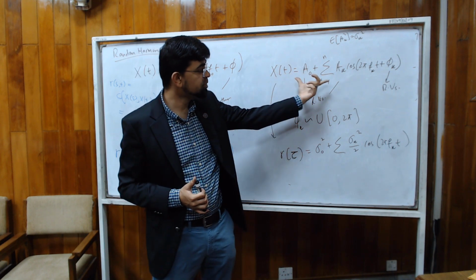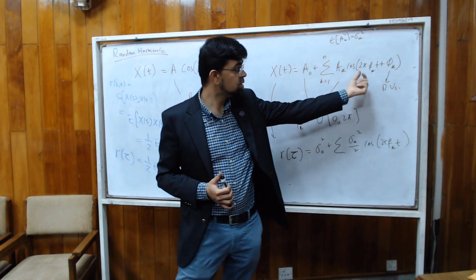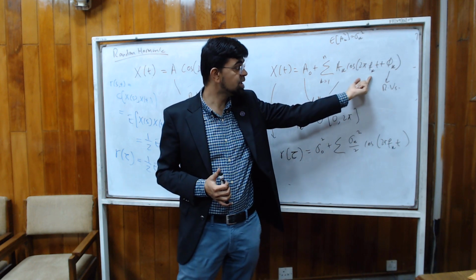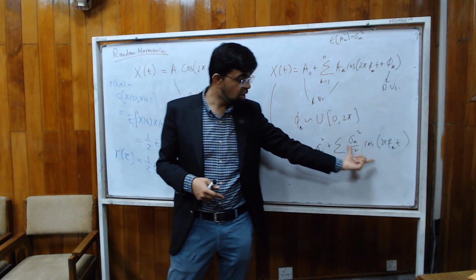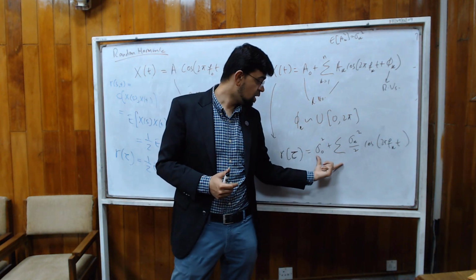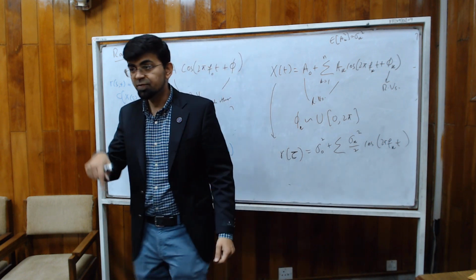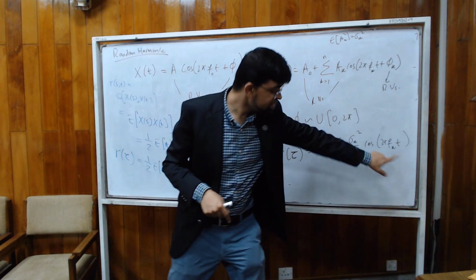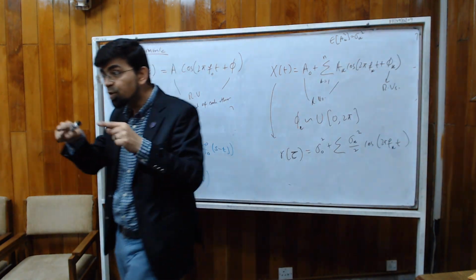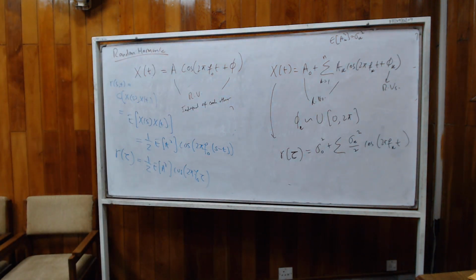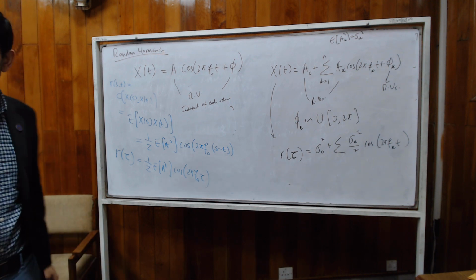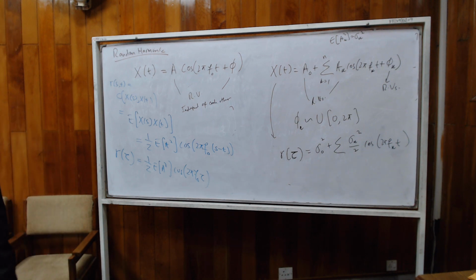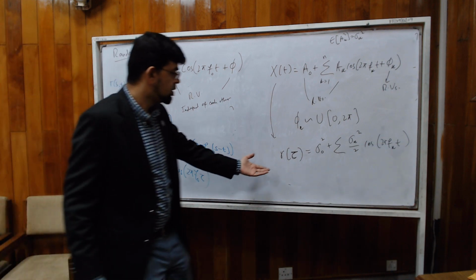If x(t) is a sum of random sinusoids with these conditions, of course, that have frequencies f0, f1, f2, then their covariance function will also be a sum of sinusoids, not random, and with the same frequencies. So if you take the Fourier transform of this, you can still see the frequency content that was supposed to be there in the original random process. That's a very powerful thing in studying random processes in the frequency domain. We will use a conventional Fourier transform on this covariance. Because it's a deterministic model.